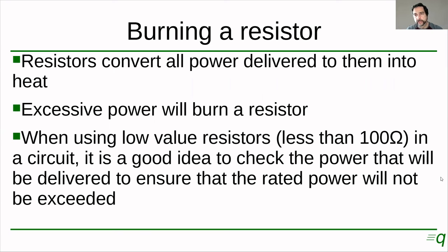If you have high value resistors like 1 kilo ohm or higher, you will not be able to exceed the quarter watt in circuits with low voltage, like 5 volts or 10 volts.